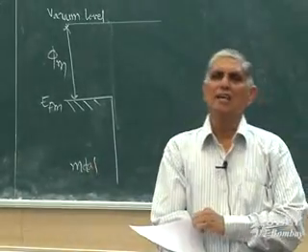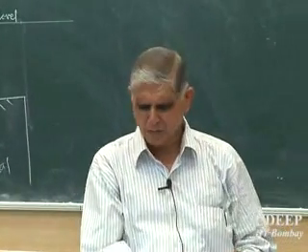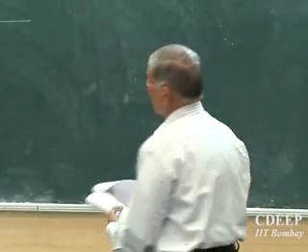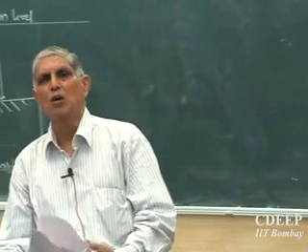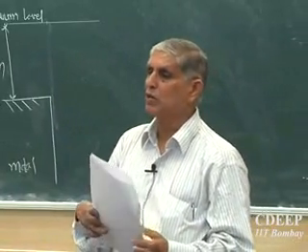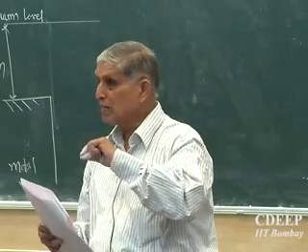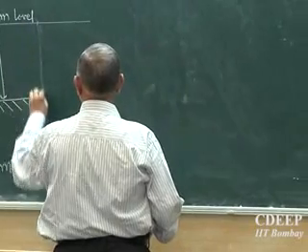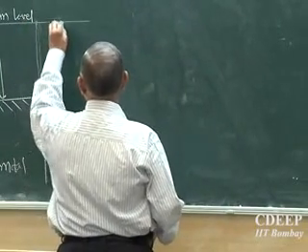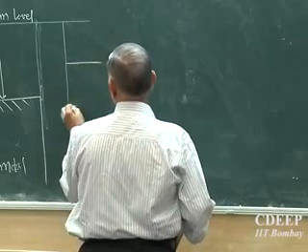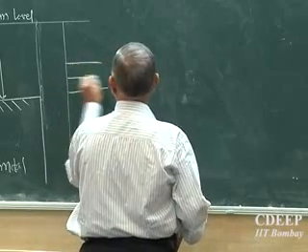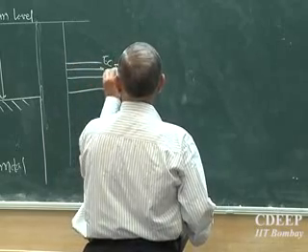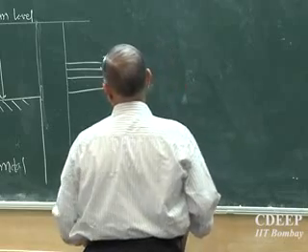So every material has a work function. Is that clear? It's not just metal; any material, you name one and we'll have this. Let us say I have a semiconductor like silicon, whose work function is then defined from where to where? From the Fermi level in the semiconductor to the vacuum level. So let's put this dotted line somewhere here so that I know where I am. Let's say this is my EC, EV, EI, and this is my EFS.